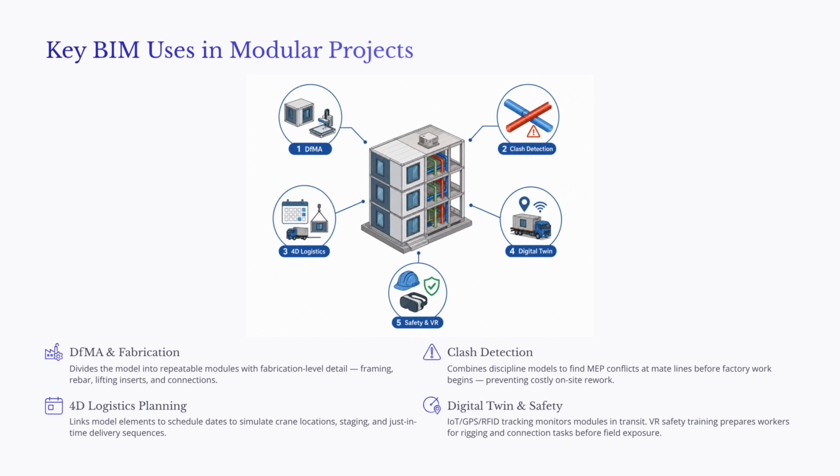Third, BIM supports 4D logistics planning. By linking the model to the schedule, the team can simulate crane locations, swing radii, staging areas, delivery sequences, and installation order. This is especially important on tight sites where just-in-time delivery is required.